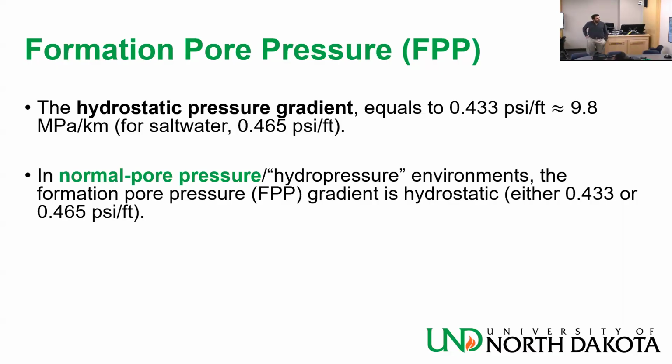So when you are answering a question in an exam and you see the word hydrostatic or something, you need to understand the context of what it is asking, because it can cause confusion. If I give you a reservoir to work on and it's 1,000 feet deep, don't assume that it's 0.433 times 1,000, and then you tell me that the reservoir pressure is 433. It's not the case. The hydrostatic pressure gradient is not necessarily that. Now, if I say it's normal, assume that it's normal pressure, you can assume that it's hydro pressure. I know it's very confusing, and sometimes I fall into these traps, but make sure.